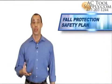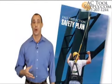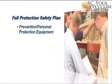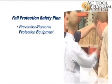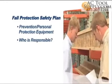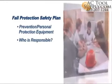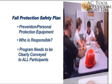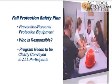A written fall protection safety plan should be created once the specific fall hazards have been identified. The plan should specify what fall prevention or personal protection measures are to be used, and it should also identify who is responsible for implementing the safety measures, including supervision and training. The program needs to be clearly conveyed and understood by all participants.